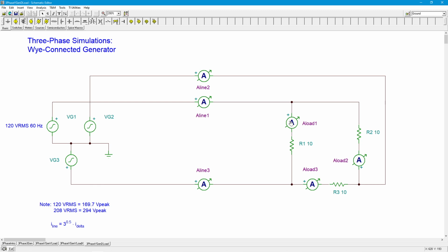We should see 3 currents, right? These 3 out here, these load currents, all sitting around 30 amps peak, and then 3 line currents. Again, it's going to be shifted, one-to-one, by like 30 degrees from these to these, or these things to these things. But again, 120 between the set, 120 between this set.